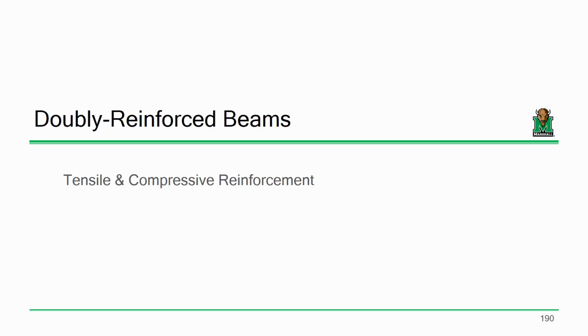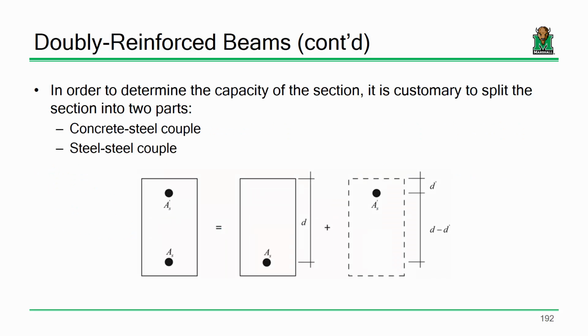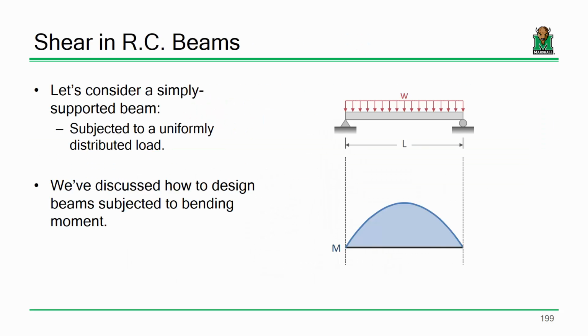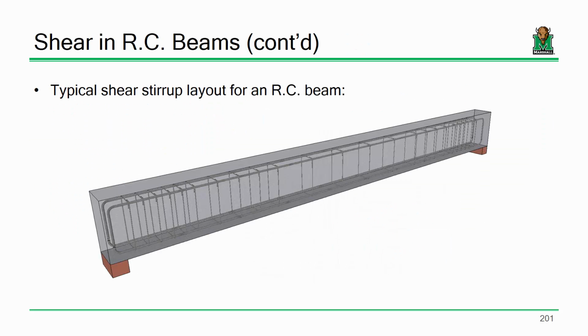Like if you're needing to use double amount of reinforcement to meet moment capacity, you either have some stringent architectural requirements or something's wrong with what you did initially. So it's not really as big of a concern from a design standpoint for me. But there are some benefits from an analysis standpoint to at least considering the fact that you have double amount of reinforcement. Now, I don't know that I have a good picture in this initial slide, so maybe I'll go to my shear lecture notes.